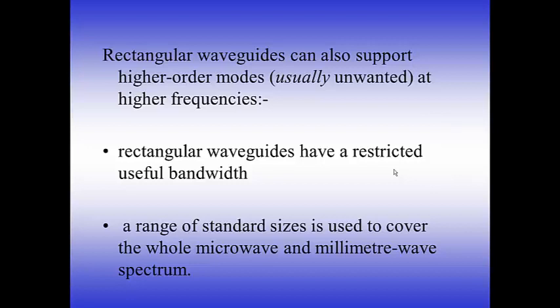Now, unfortunately, if you go up to higher frequencies, you find that the rectangular waveguide starts to support even more complicated propagation modes, so-called higher order modes, which are usually unwanted, and that means that rectangular waveguides have a restricted useful bandwidth. At the lower end, you're restricted by the cutoff frequency of the fundamental mode. At the higher end, you're restricted by wanting to avoid these higher order modes. So there has to be a range of standard sizes of waveguide to cover the whole of the microwave and millimeter wave spectrum.